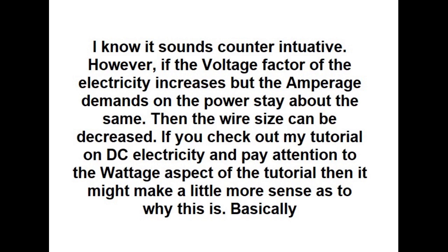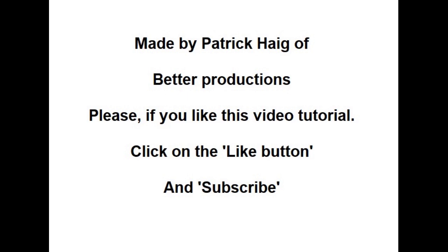So you might want to go out on Google and look for a DC wiring voltage calculator. Into that calculator, you'll need to enter the length of your wire, or the projected length you believe you might use. You're going to have to enter the amperage, or the maximum amperage you believe you might be using. And of course, you're going to have to enter the voltage as well. And it will calculate what it believes to be the ideal gauge of wire you might use in such a scenario.